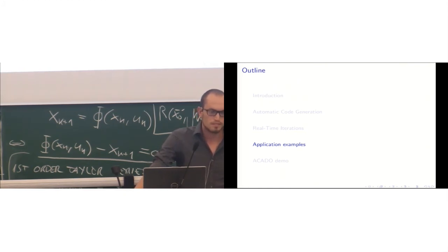Yeah, the idea is basically the asymptotic complexity of how they scale with the horizon length. There's more to it, because they also have different complexities of how they scale with the number of states and controls, and even the structure exploiting solvers have different ways of scaling with that. But as a general rule, you could take what Joachim had, where I think he said that as long as the horizon length is much larger than the ratio of states and controls, it's better to use a structure exploiting solver. Which basically means that condensing with a QP solver is better if either you have a lot of states compared to the number of controls and not too long a horizon length, or you have not too long a horizon length in general and a fair ratio.